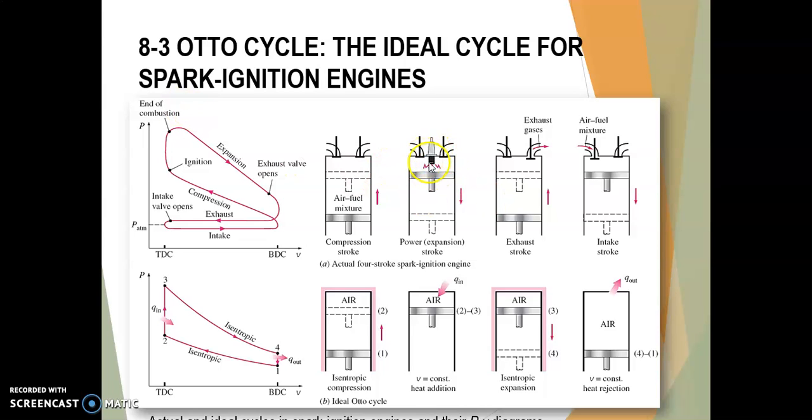So by applying the spark, the whole gasoline will get the explosion. So it will force the piston to be pushed down to the bottom dead center, and at this time we rotate the crankshaft. Then at this part we will have the whole smoke that we need to release to the exhaust. So we need to open the exhaust valve. Then the piston will be pushed to the top dead center.